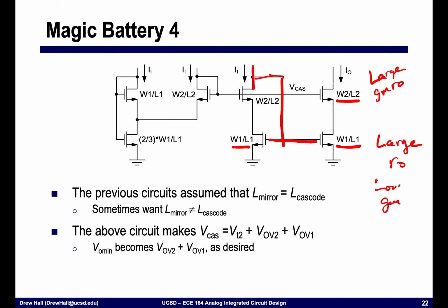But now, instead of just stacking the structures like we had previously, we need to make what's called a replica of this circuit. What we're doing here is using this device, and we're summing the currents at this node. Previously, you'll recall that this used to be a 1/3 device. Really, this is just like we have two of these devices in parallel. And that's where we get this factor of 2/3: it's two parallel devices that are giving us more width because we're dumping twice as much current into it.